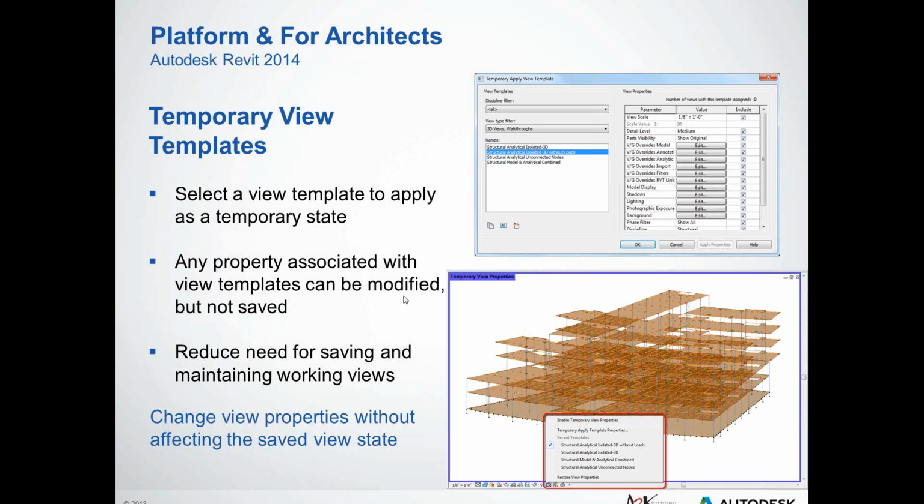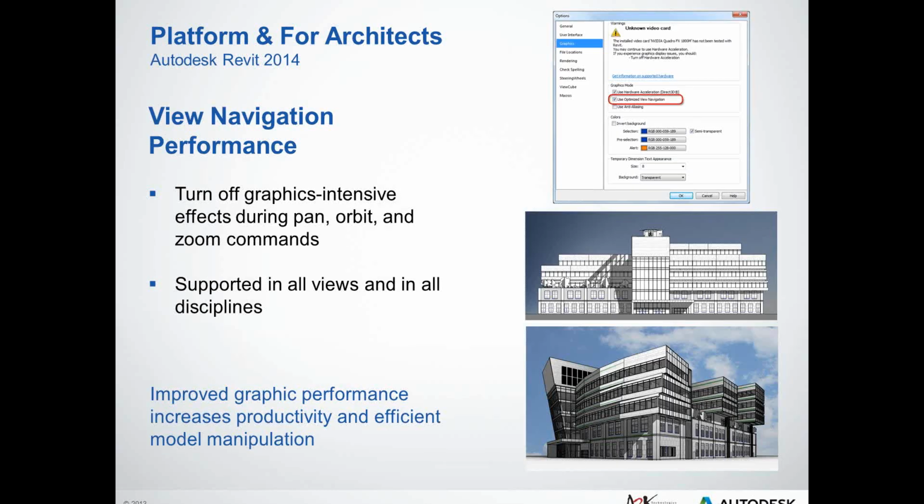There's been some performance improvements added in. This is mainly for 3D views and the likes of plans where you need to pan around significantly. The idea behind this is that as you, say, spin a model around, Revit will, on the fly, degrade that model, thereby hopefully turning off elements, maybe more complex elements that you don't necessarily need to see as you spin the model.